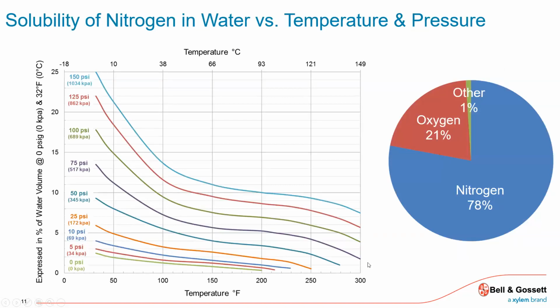air. There's a chart here talking about, because really when you get into the makeup of the air, it's 21% oxygen, and then it's about 75, 78% nitrogen. So that's the air bubbles, if you will, that are coming out of solution, because that oxygen over a short period of time will actually form almost like a corrosive layer. It'll be absorbed into the piping system and actually cause corrosion. But it's only a small amount. You've got this limited amount of water. You're not constantly replenishing, because that's where the systems get into trouble, is when we have these leaks that aren't detected and makeup water is constantly added. That means there's a bunch of oxygen that's being released and starting to attack.